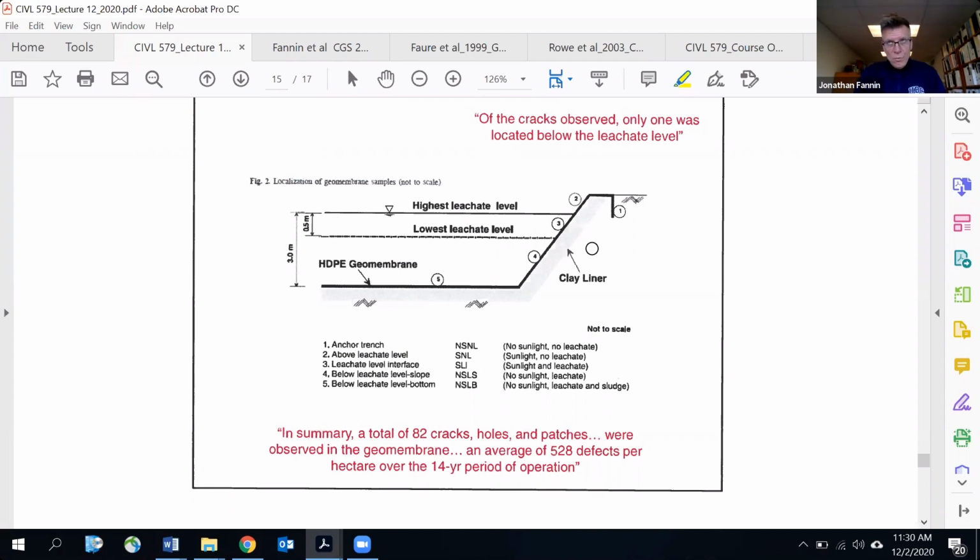And there will be defects because of thermal induced stresses. There will be defects because of thermobiochemical induced stresses. There will be defects potentially because of construction damage that's partially patched. There will be defects because if you've tested seams or maybe done some coupon testing, you may have to patch that after. There can be many and varied reasons for patching, okay?